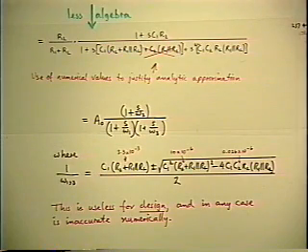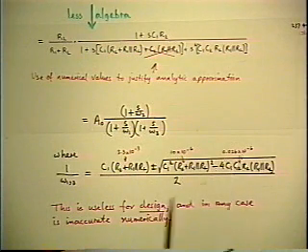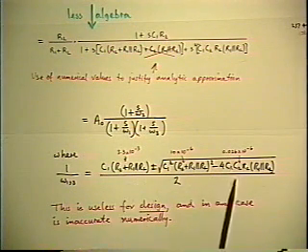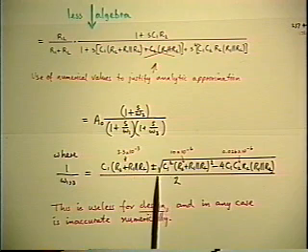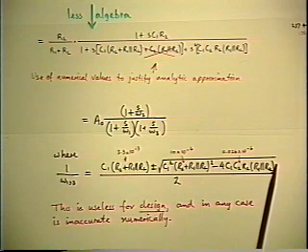And this is the other point that I emphasized in the introduction, which is, this is a high entropy expression, and you might as well not have bothered to write those symbols in there because they're worthless. You might as well have put the numbers in right away. And I've written over the expression what the actual numbers are. And the conclusion is, this result is useless for design because you can't work it backwards. Knowing what the two corner frequencies are, it's hopeless to try to solve for any element values.